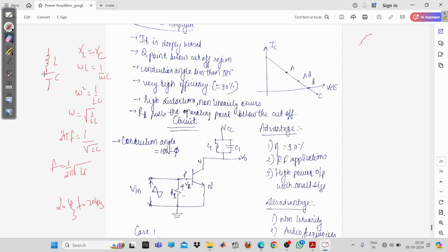So what is going to happen now? If you want to calculate the effective impedance, it will be equal to what? That is J into XL. I'll rub this portion because we have got the resonant frequency. Now, if you put down the values, you are going to get the resonant frequency. So this is JXL, and then plus minus J into XC at the resonant frequency.